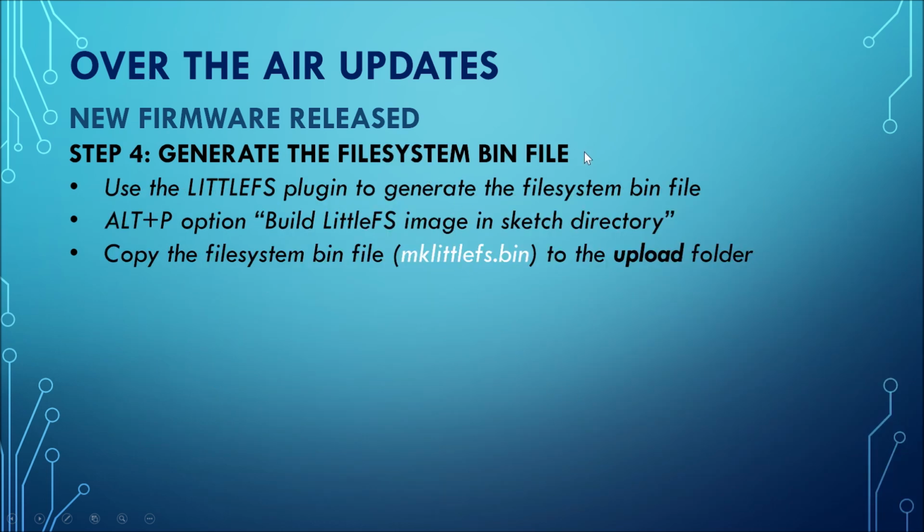To generate the file system bin file, we've already got the Arduino IDE running. So we press Ctrl+Alt+P to bring up our list of options, but instead of selecting the upload to ESP32, we select build LittleFS image and sketch directory, and what that does is it generates a file called mklittlefs.bin in the actual firmware folder itself, and then we copy that to the upload folder.